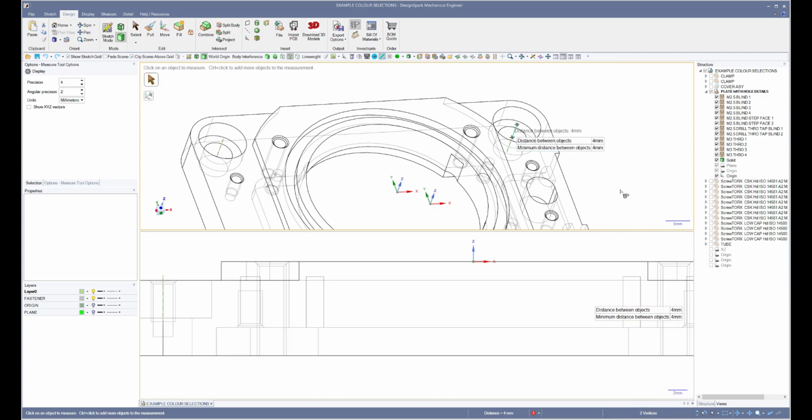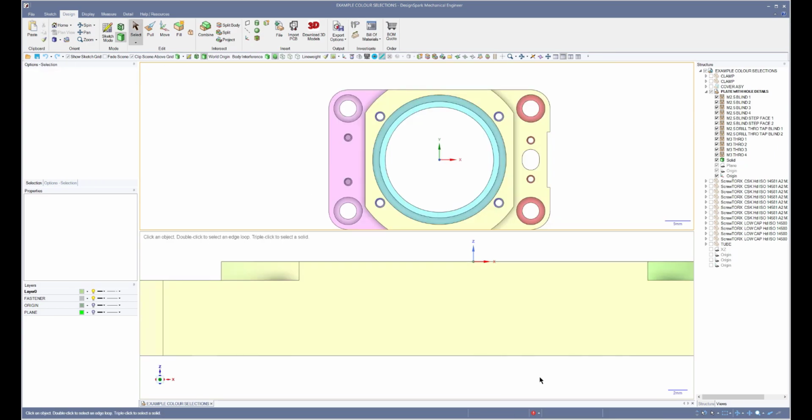Vertices do show, however, in other operations such as move and pull. And with regards to objects which can be easily selected, we have a selection filter. Now at the moment it's on Smart, and to see what is actually under Smart, if I select this small little drop down arrow, you can see it changing to blue color. You can see that my Smart menu is going to pick up all of these objects, faces, edges, sketch curves, etc., but bodies have not been selected.